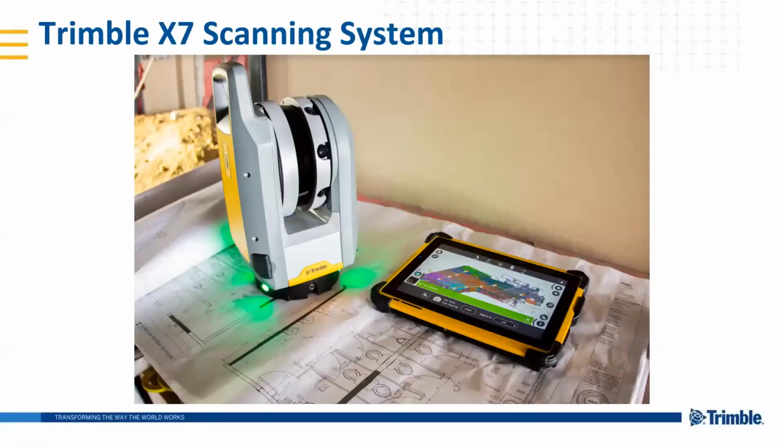This is an X7, which comes with 500,000 points per second. It has 5 onboard cameras, 10 megapixels each for imaging. So you are basically creating photogrammetric evidence as well as point clouds. And it is all self-leveling. It has a collimator inside, first of its kind. It balances itself even at angles of 45 degrees. So there is no learning curve in order to operate a laser scanner like X7.